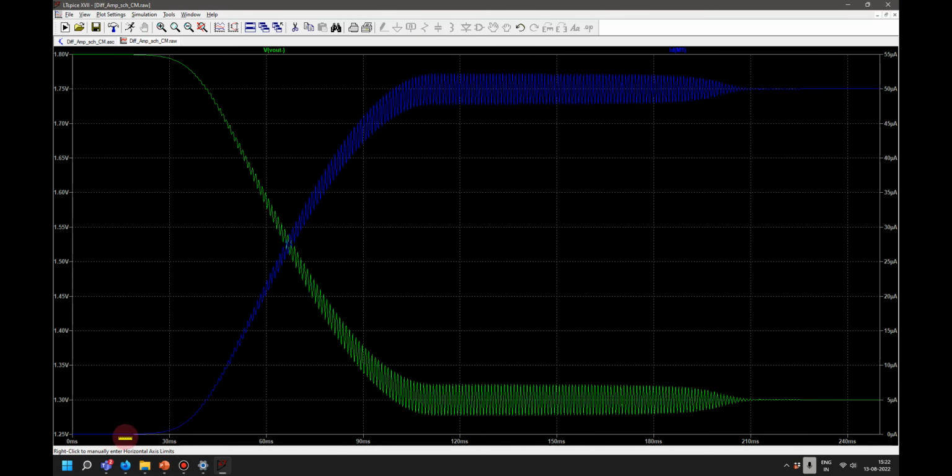See, initially there is no current, right? And then the ID current is established, 50 microampere, 100 microampere. Once the 50 microampere current is there, in this region I have maximum gain. Here the current is 50, but the transistor is coming out of saturation, because we have seen the common mode range. It can't go beyond that, otherwise the transistor will come out of saturation. So here it is going out of saturation, and again the gain is going down. So this is the useful range for us, the common mode useful range, you can see from this graph.